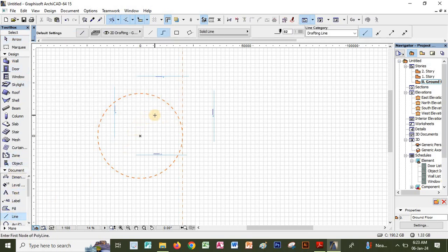So, and I want to use the tracker. So if I want to input by distance, I can click D, or by angle I can click A, or if it is X and Y or Z, I can just click X or any of the other that I want to input, and then I say 0, Y, 0, it has been tracked there.